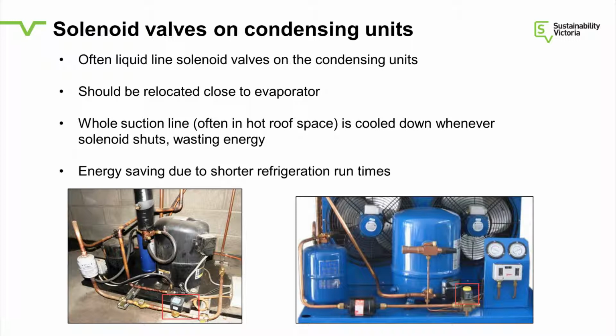And that's entirely okay. Now, what happens when the solenoid valve shuts? As soon as it shuts, between it and the expansion valve, all that liquid still keeps flowing. All that liquid empties out through the evaporator. So if you have your solenoid valve far away from your evaporator, all that liquid still has to empty out, and your compressor has to run that excess amount of time. And what actually also happens is that liquid line itself becomes cold. So if you have your solenoid valve far away from your cool room, you're actually cooling the environment and you're running a compressor much longer than you should. And that is very inefficient.